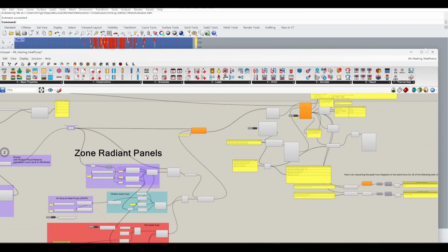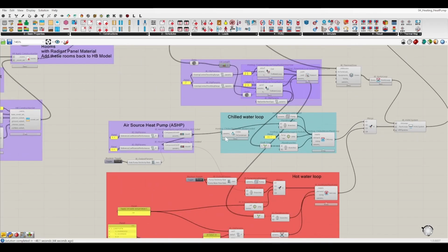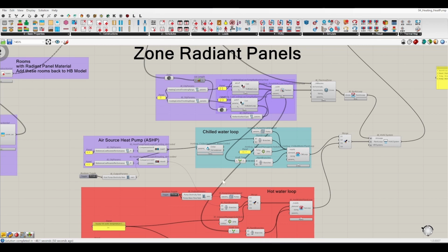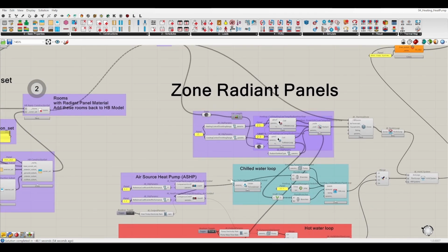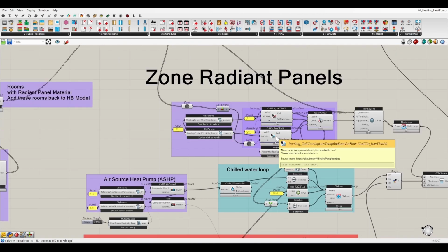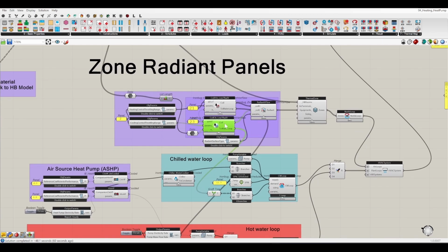So I guess we can definitely look into this system in more detail. But I think the radiant panel for the cooling doesn't work for this case, or doesn't cool the room enough for the space. So let's see if we can find another alternative. So the radiant system for the cooling won't work, so we can try to use the air-based system.